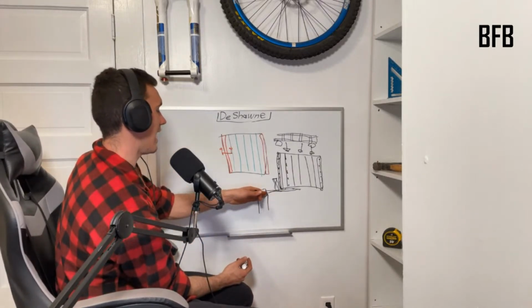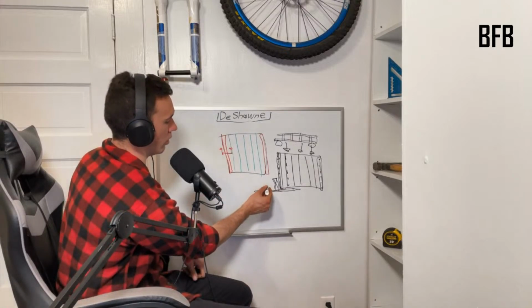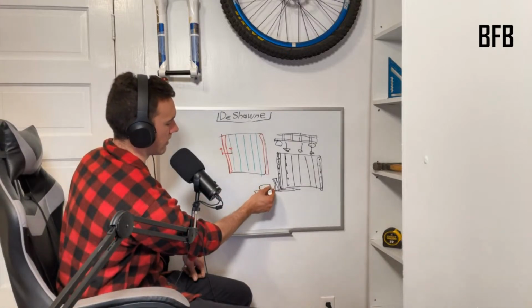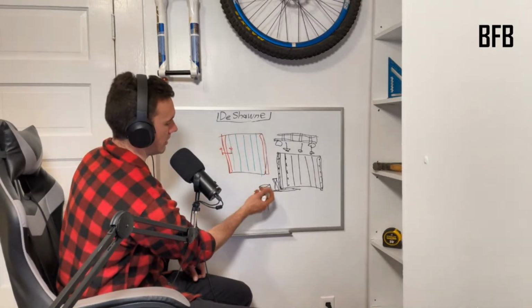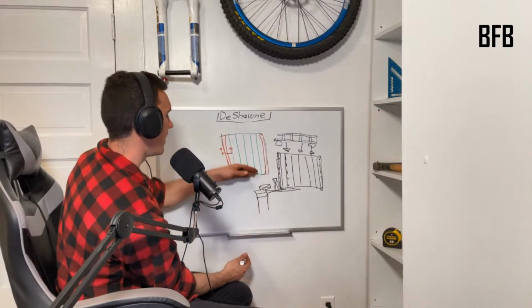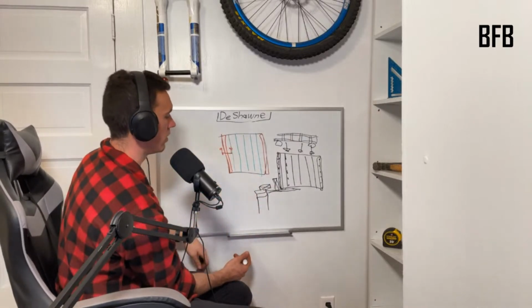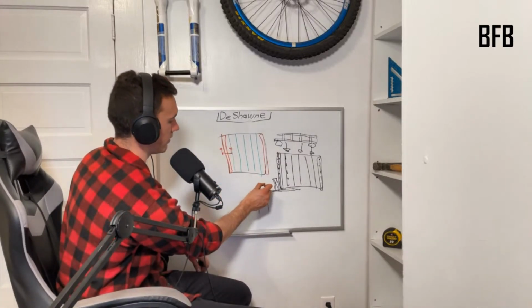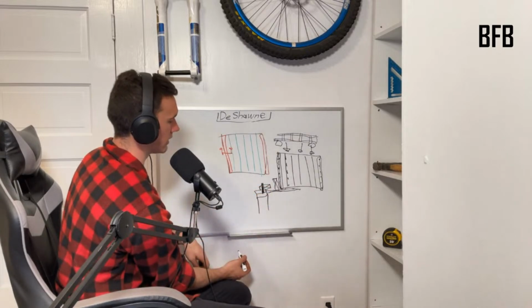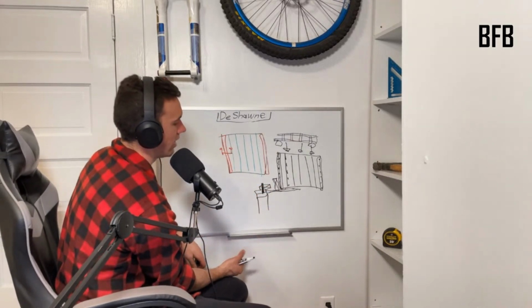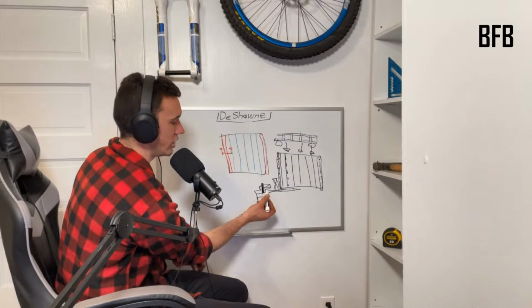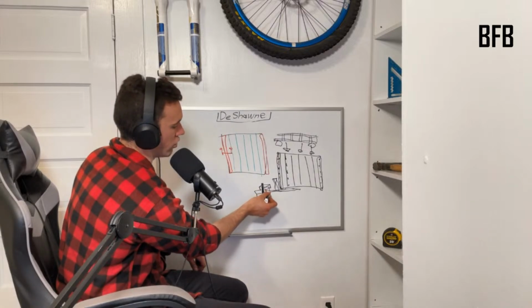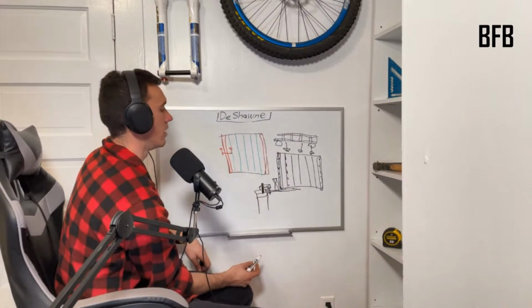Well, you don't want to leave it hanging over here. So what you're going to do is take a block of wood, usually 2x4, 2x6, like that. X means cross section. And you're going to lay it flat on your wall. You're going to screw it or nail it down right here to the wall, connect it. And then guess what you're going to do? You're going to take sheetrock screws and screw it all the way down the sheetrock board, all the way down the wall.